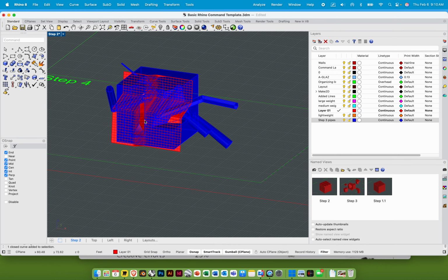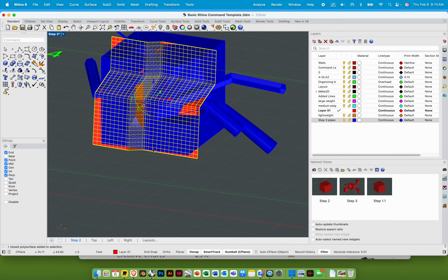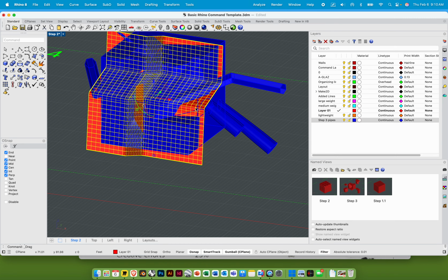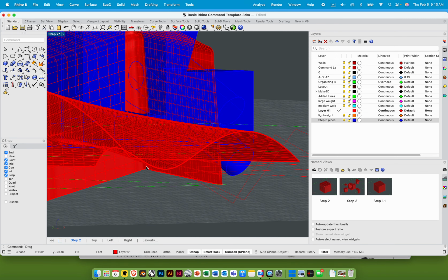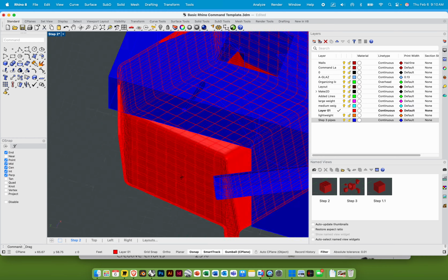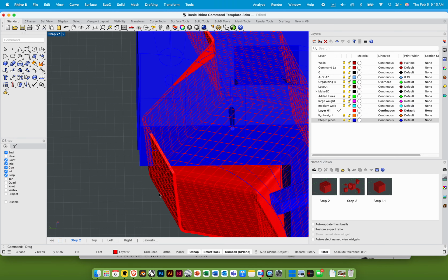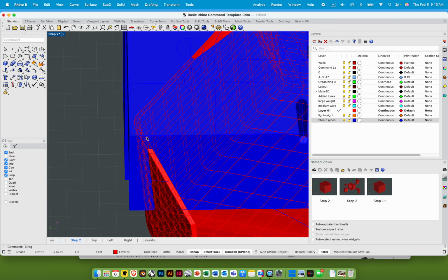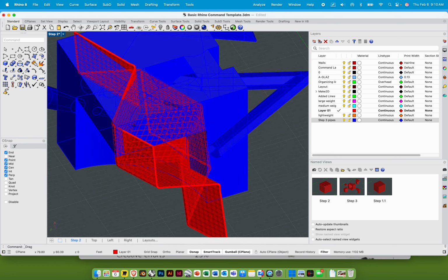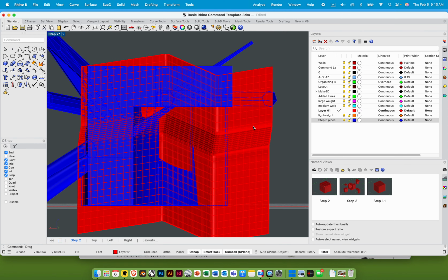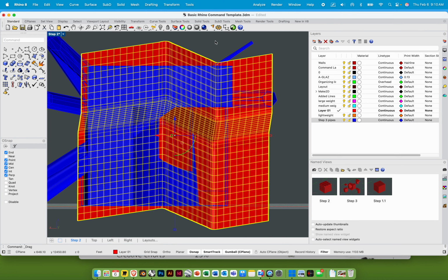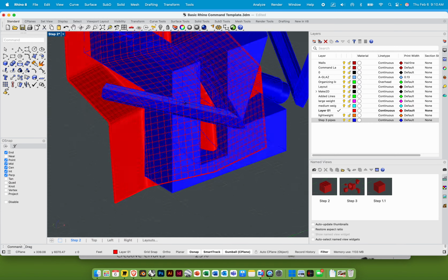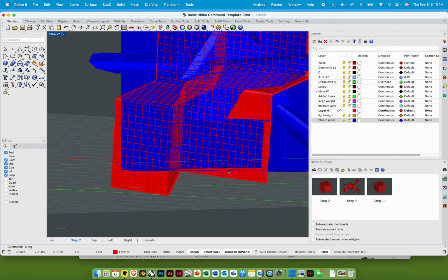So in my case, I might have to fake it till I make it a little bit and make it a little bit bigger, right? That way, I know that it's actually completely exiting the object, just like wire cut or some of the other operations, where it's both going in and out of the object. That might not work either because it's technically not two pieces. So I may need to move it up a little bit, and that's okay.